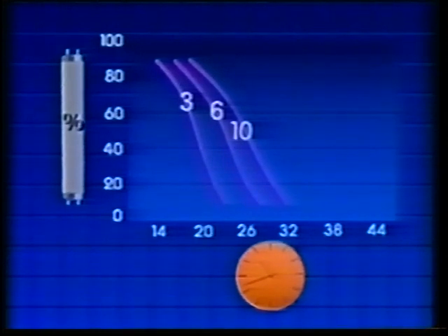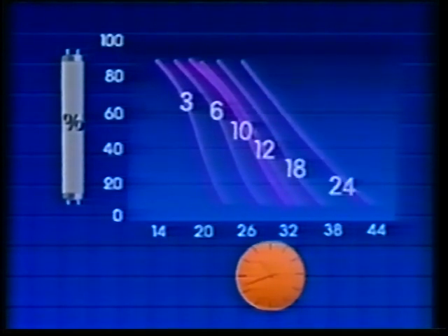For example, a standard 40-watt fluorescent lamp is rated at 20,000 hours average life when using the 3-hour cycle. Extend the cycle to 10 hours, and the life rating is increased to over 27,000 hours. Burning lamps continuously would result in an average life of over 37,000 hours. Half would burn for a shorter time and half longer.